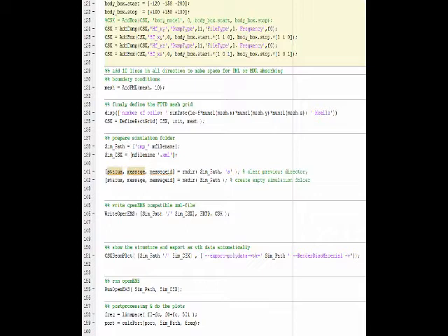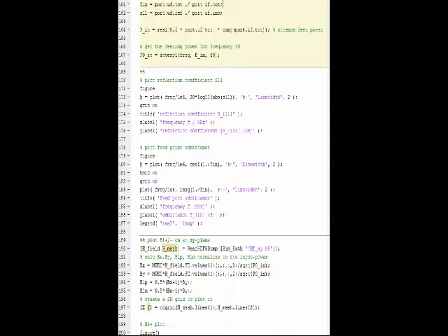To show the structure and export it as VTK data automatically, we use the function CSXGeoPlot to create the geometric plot. And then we finally run OpenEMS. Therefore, we can see the whole structure using the function run OpenEMS, taking the directory and simulation file CSX as input. From line 157, we are doing the post-processing part.